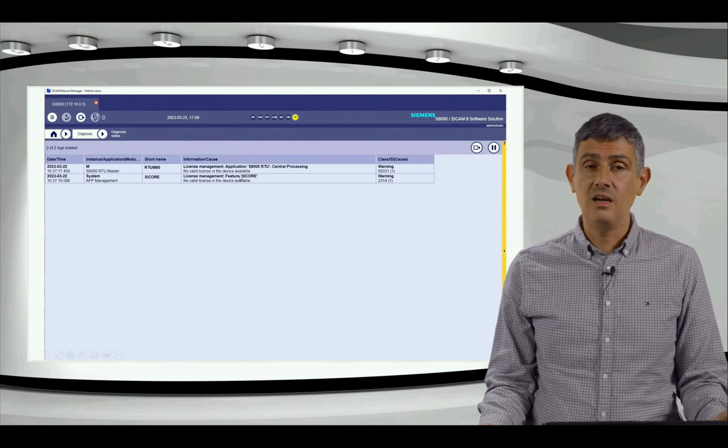We will need an additional graphic for the event list. So we click here on the plus on the graphics. And we select the title, the event list total, and we select this is only events, and we confirm it. Now we have here a new graphic, event list total, and we see in the middle that we have a warning telling us that no event list assigned.